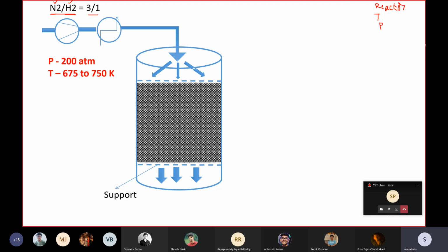So here we have a sprayer that distributes across the support plate so that the reactant flows throughout the reactor uniformly. We have a uniform spray distribution system that will ensure the reactants spread across the top distributor plate so that the reactant can flow over the reactor uniformly.